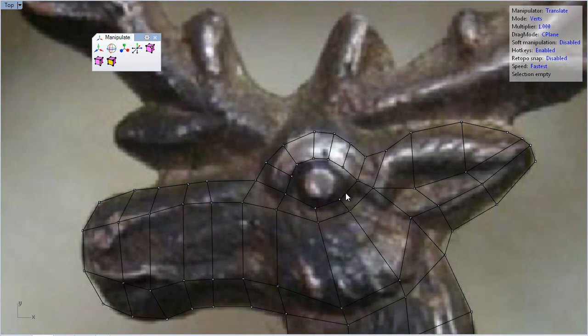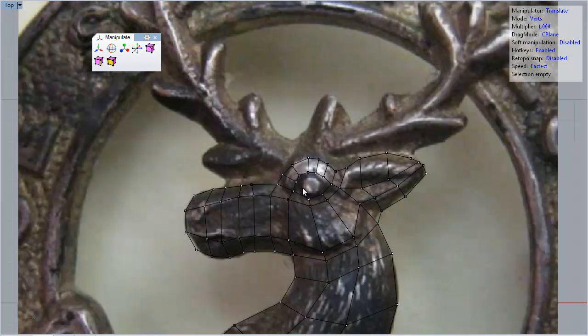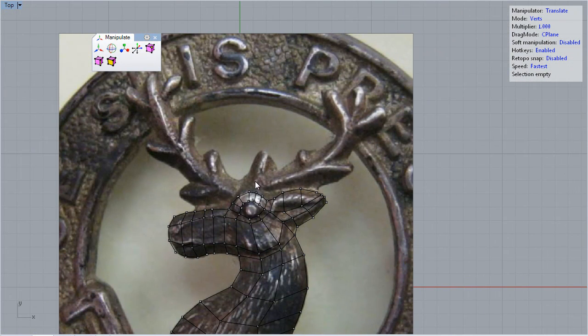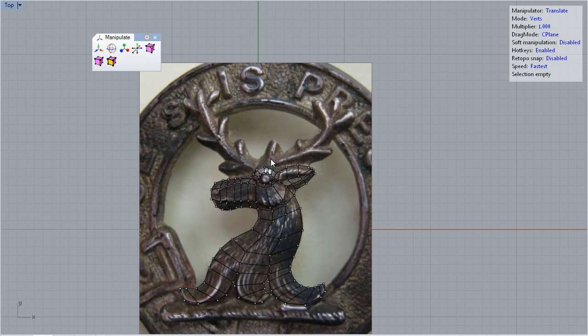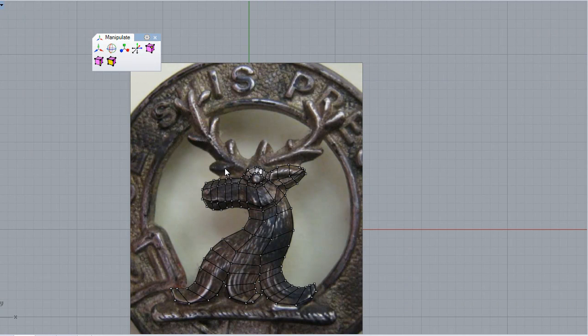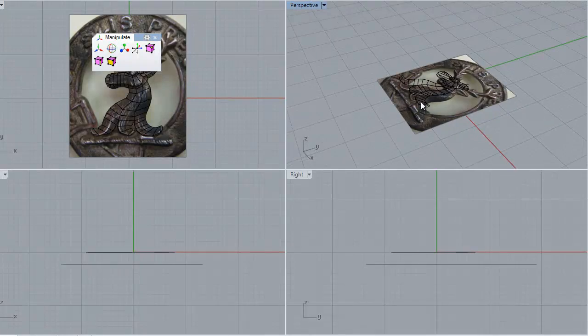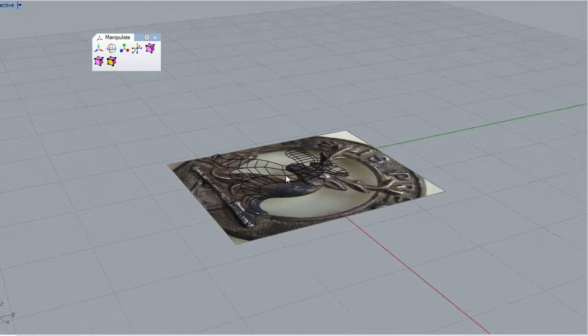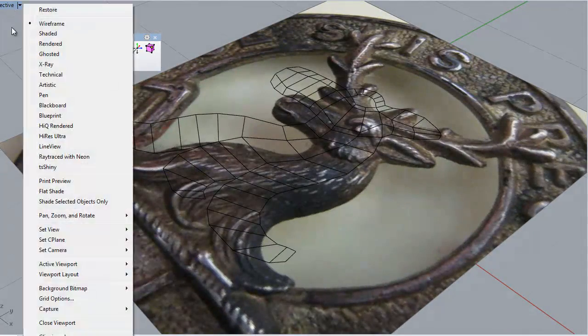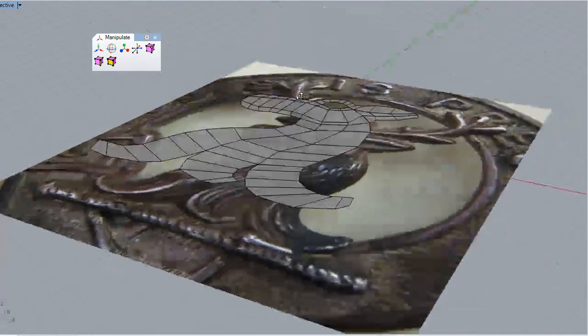And then I'm going to put a sphere in there for the eye, to finish up the eye, and I might use pipe, the TS pipe, to do this section. Alright, so for now let's do an extrusion of that and see how we go. Okay, so I'm going to work in that view. I'll put on my ghosted viewport.